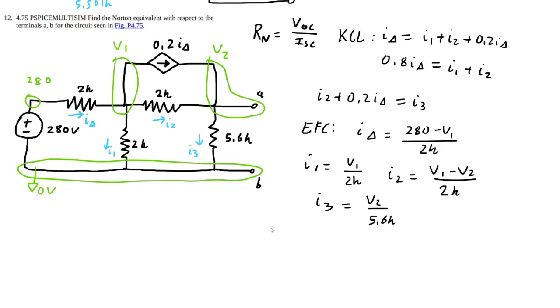Alright, so I'm going to go ahead and short this, find our I short circuit current. So it's going to make this 0 volts. Anytime we see V2, it's going to be 0, so I3 goes to 0, because 0 plus I short circuit. So if we can find I2 and I sigma, then we will find I short circuit.